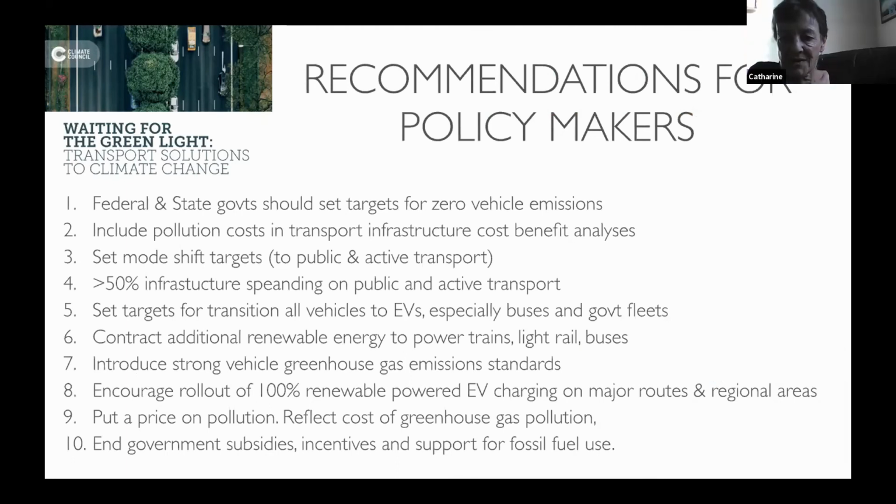Great. Okay. Question number 1. Does the rapid charge wear out the battery faster than slow charge? Yes, it does. Batteries obviously are stressed more if you rapid charge them. Most electric cars have cooling systems in them to keep them cool, because that's the important thing. When you rapid charge, they tend to get a little bit warmer, and the charger itself gets warm. Yes, the answer is it is better to charge more slowly.